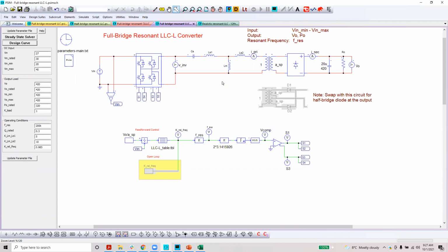So if you want your nominal to be at resonant, but you don't want to sacrifice the gain if you mismatch some turns ratio, in that case, this topology helps a lot. You can always play with the two inductance ratio, air gap here to get the amount of gain you want.